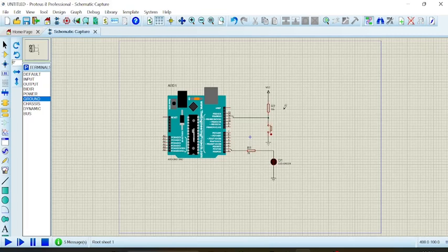The reverse occurs in the pull down mode. The pull down mode, when you have the push button up and the resistor down, you will notice that the push button up is always open and so no current flows from the source VCC here to the microcontroller pin.